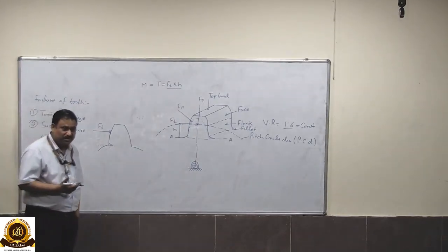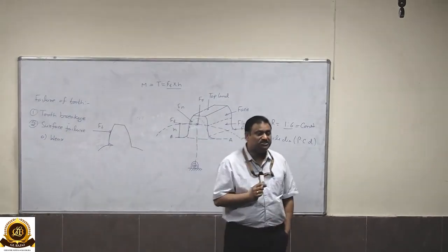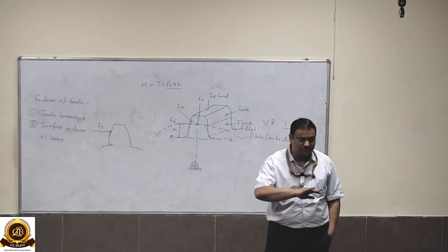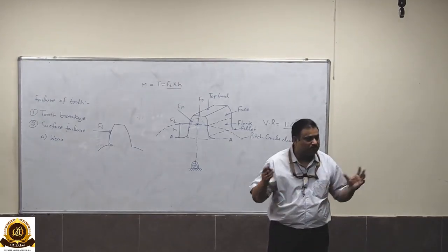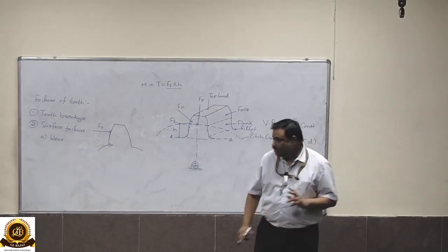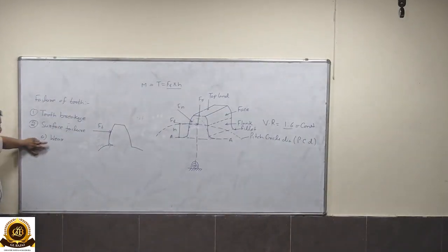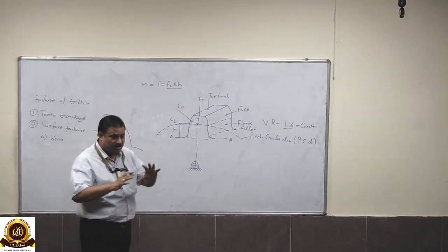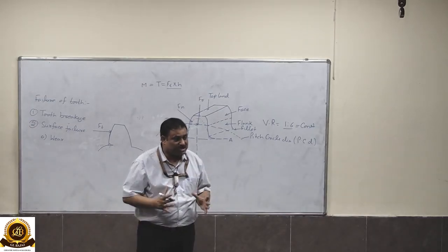Now wear is basically of two types. One is the initial wear, which starts just because of a manufacturing defect. If any remaining particles are present on the surface of the tooth, wear takes place initially and the material is gradually removed from the surface over a period of cycles. But this will also increase because of abrasive or foreign particles. Suppose your gear train is working without any casing, in the presence of dust particles.